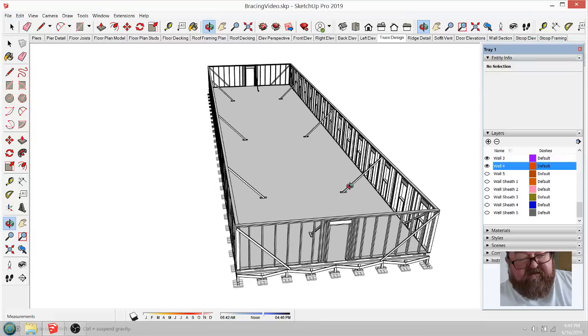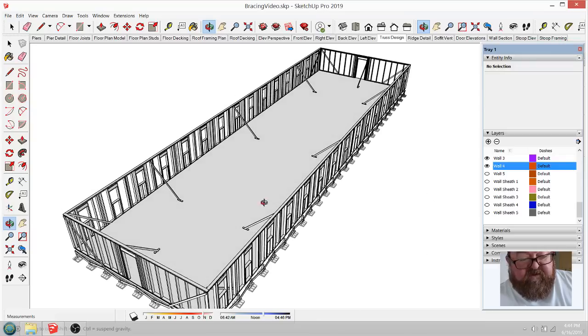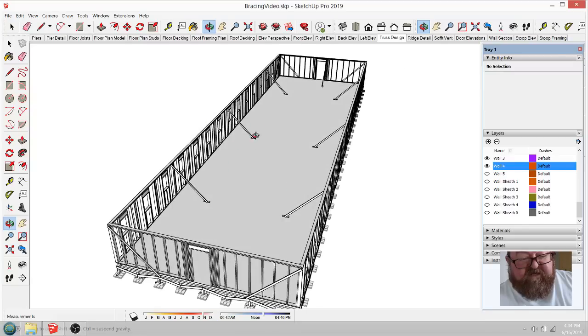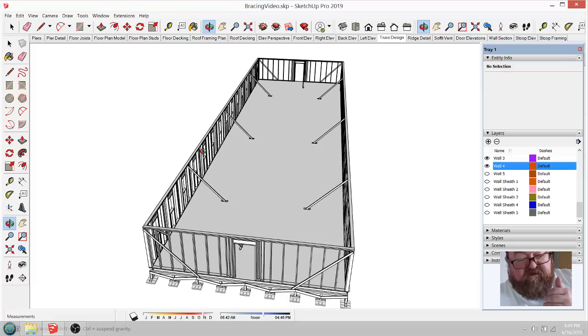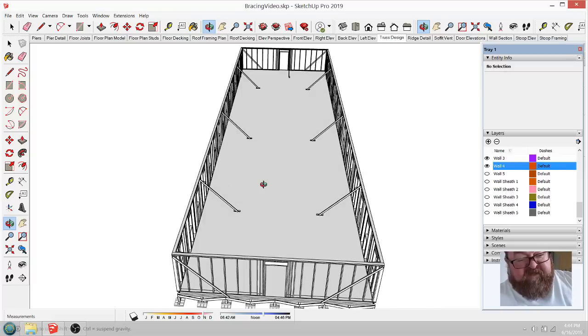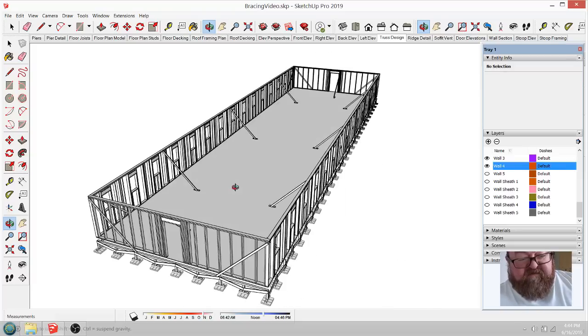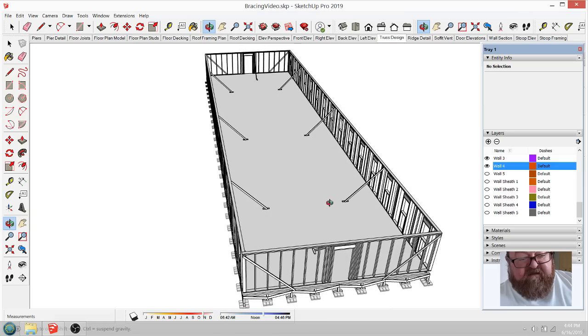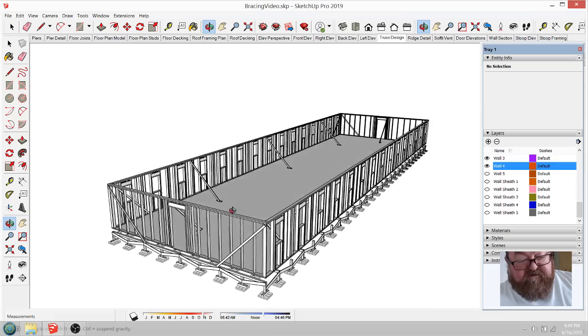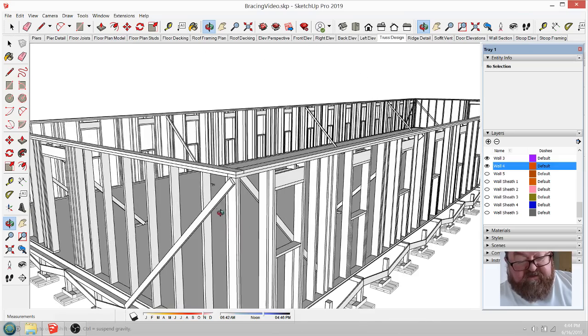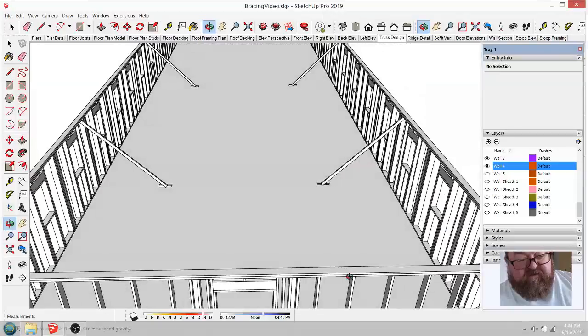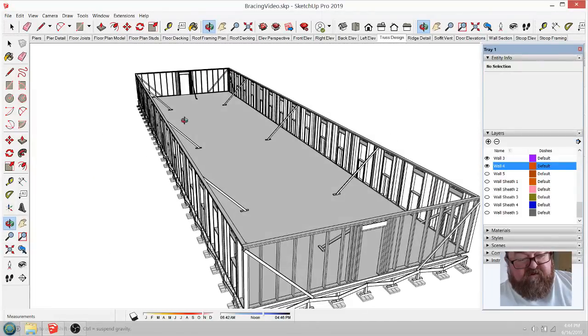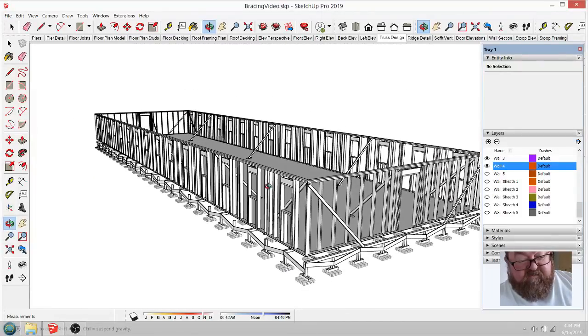It's fine, right? If you're doing these walls in sequence, and say you only get 2 walls built, let's say you just get this wall and this wall built, okay, and you have it braced off properly, it's fine. You can leave it overnight. No harm done. You absolutely do not want to put any sheeting on this wall until you are finished framing up all the walls and bracing it off.